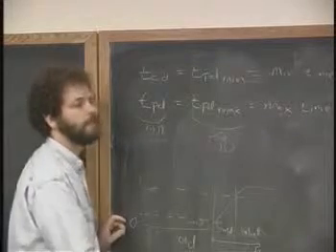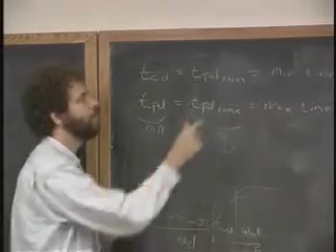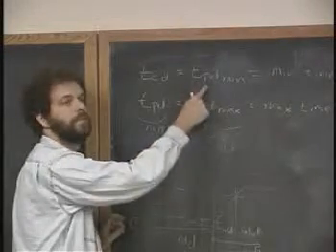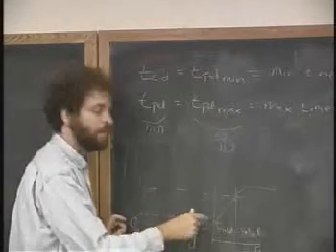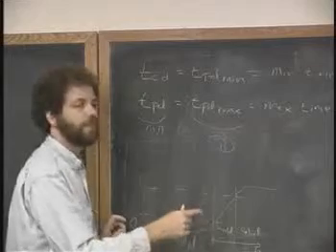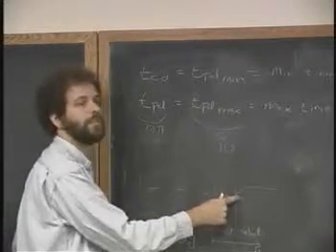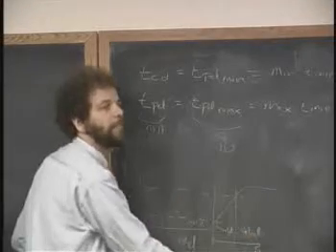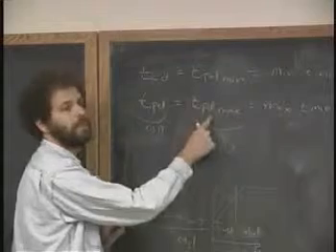Well, the answer is that it guarantees it will continue to produce the old result for at least TPD min, the minimum amount of time for invalid stuff to propagate through the circuit. And then the question is, once I finally send it the valid new stuff, how long does it take for the valid new output to happen? The longest that could take is TPD max.